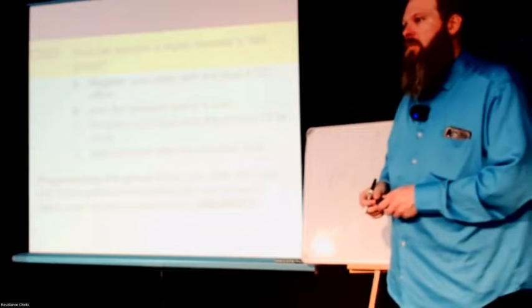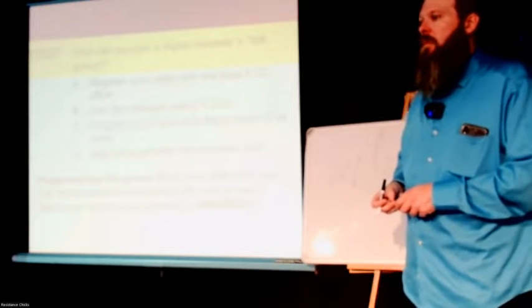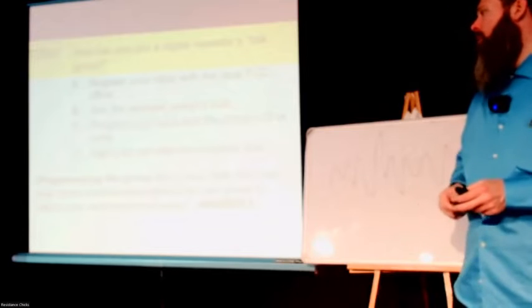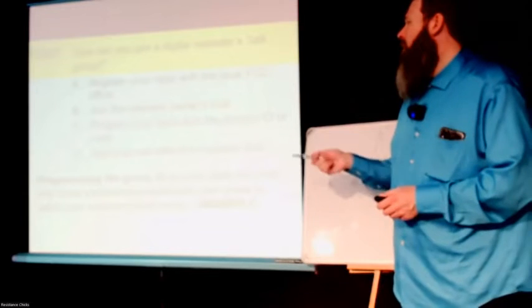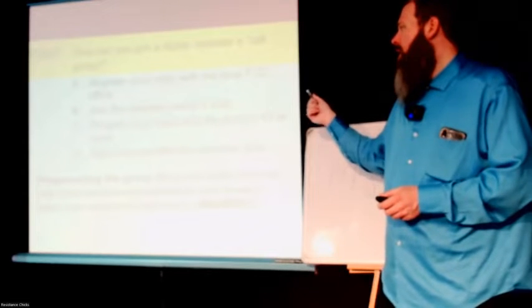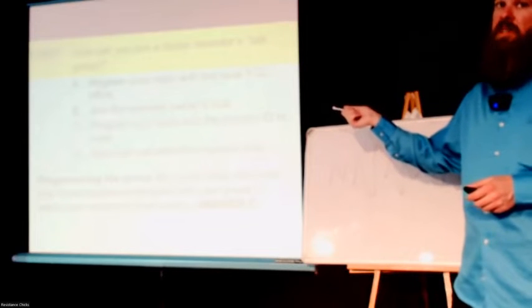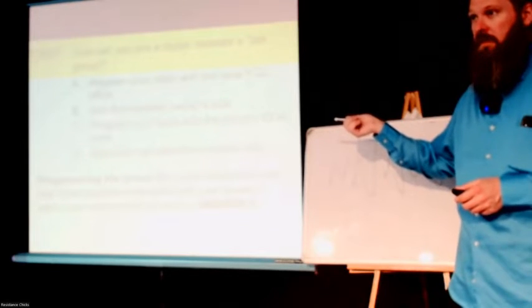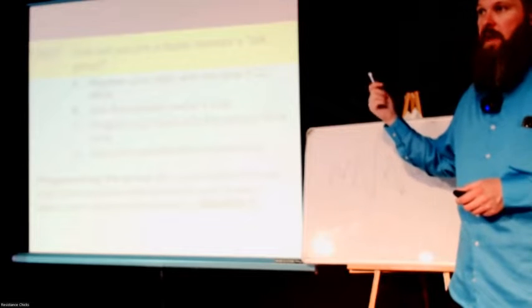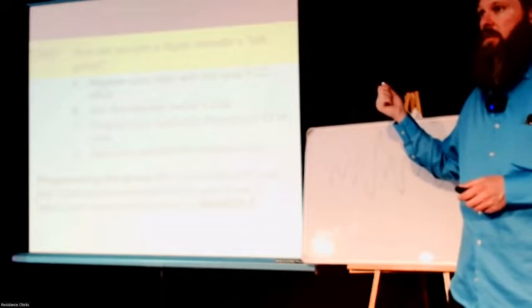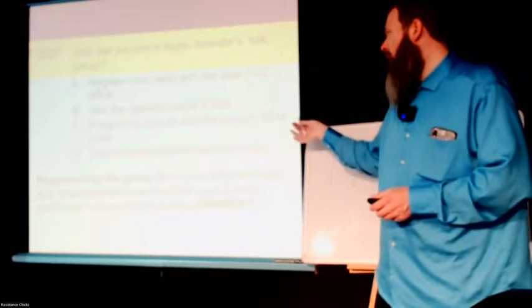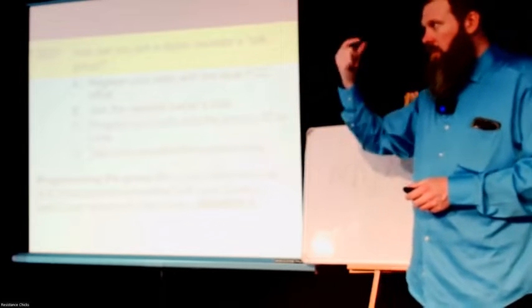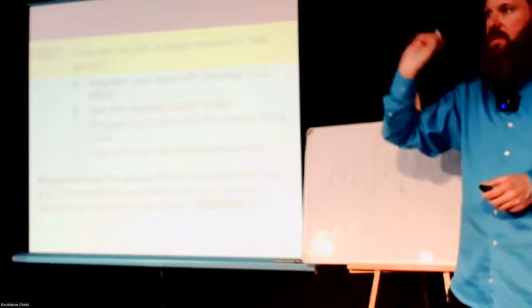So what are you actually doing? You're programming the frequency for a certain time. No, so what this would look like is you would find a DMR repeater in your area. Then you would look up the group ID for whichever group you wanted to talk in and program that into your radio. And then when you transmit, the repeater would receive that digital data, because it's digital radio, and say, oh, you want to talk on this talk group? And it would put that voice into that talk group and send it over the internet to all the other repeaters that are participating.